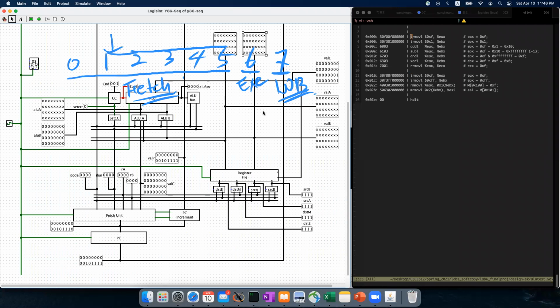Right. Also, this write back is part of the decoding unit, but the writing back should happen at cycle 7 or 8th cycle. Why? Because the execution unit produces the data for write back. So this is the challenging part for you, to make all these components work together. Also, this cycle information works for only this version.